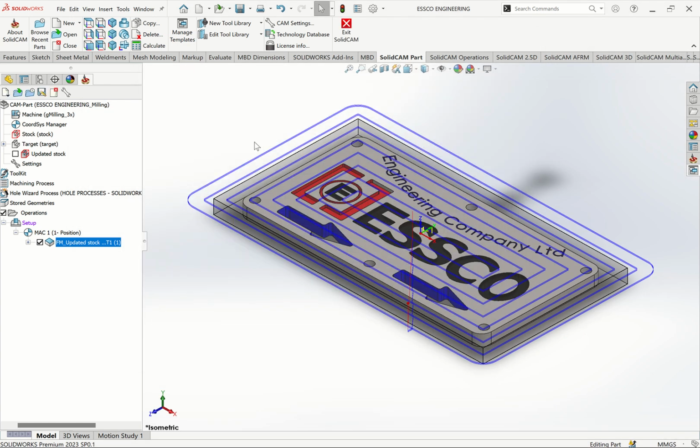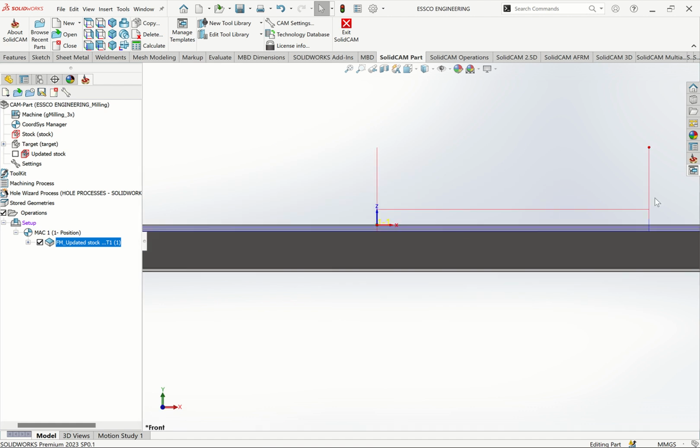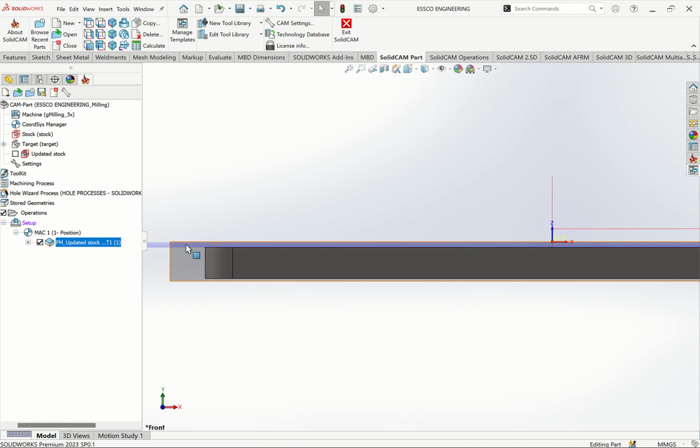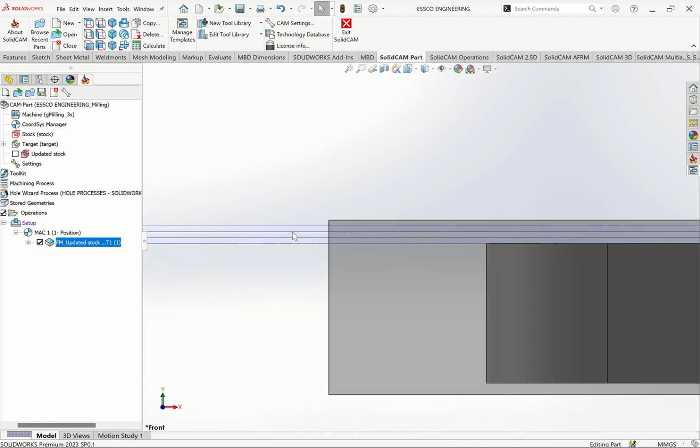If you're able to see this, these are the toolpaths. If I click this Ctrl 1, you see the red ones, these are lines, which means the tool is approaching from this one and going all the way. So the red one is the tool approach, the blue one is the tool cutting. And then how many passes it will go. So this is the first pass, second pass, third pass, fifth pass. If we're able to calculate, I've put 0.5, and remember you have 2 millimeters.